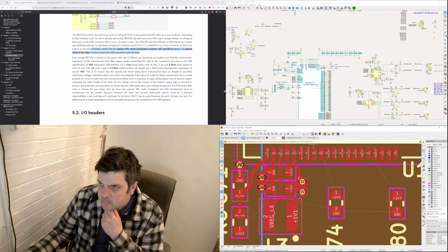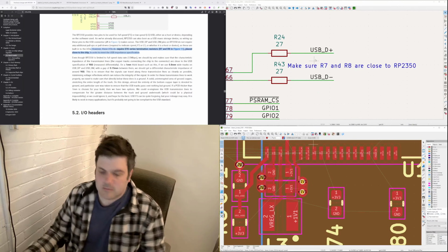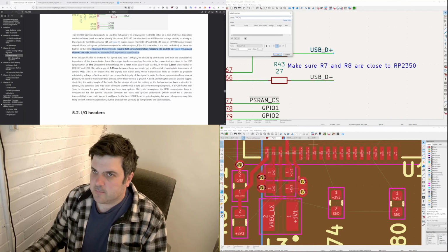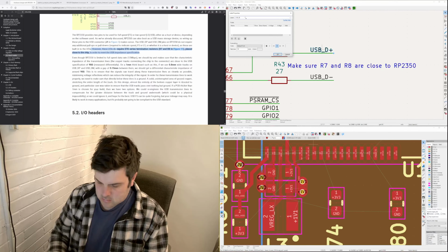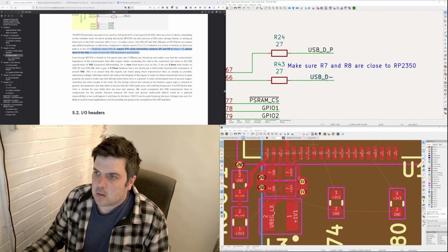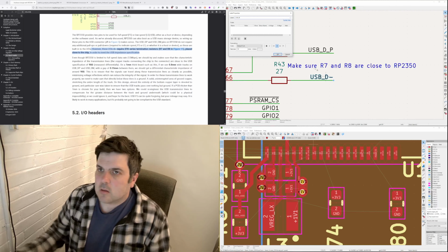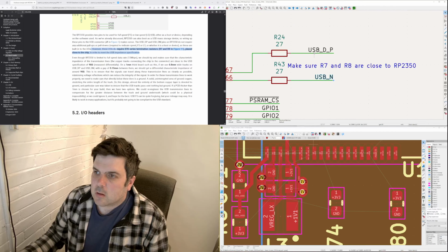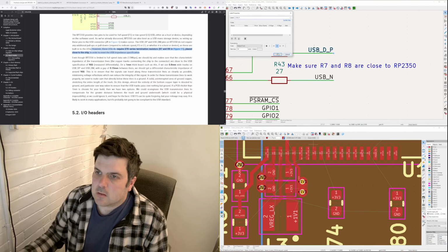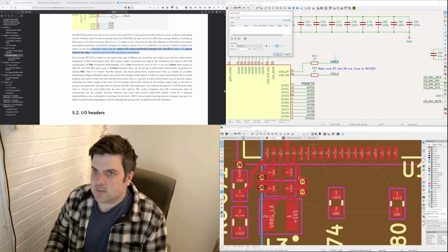I'm able to find a pair of nets because you have to label them with N and P. So what you have to do in KiCad, if you want to use a differential pair, you have to call them positive P. USB P. No, let's call it D because it's called... let's call it DP.